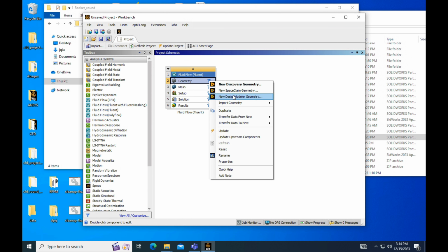So we go into models and we turn on the energy model. This will be so we can set the air properties to an ideal gas, which will make our calculation more accurate because we will initialize from the far field using a Sutherland calculation for the viscosity properties. Let's press OK. Change, and we'll close that up.